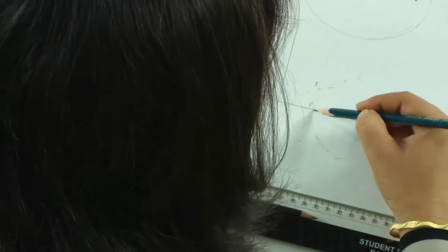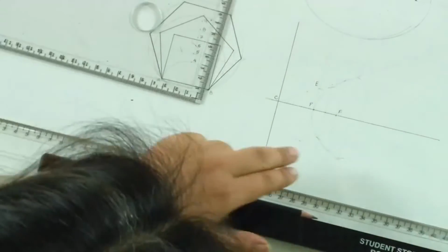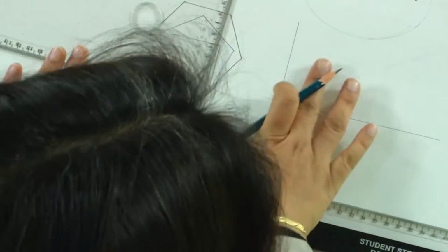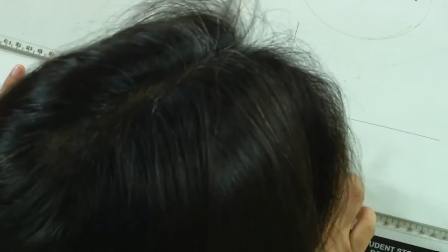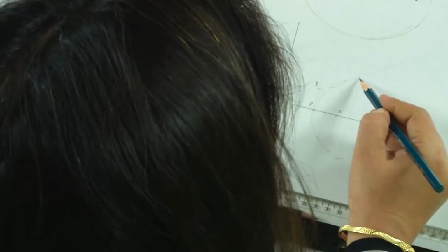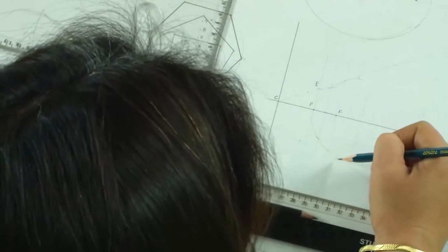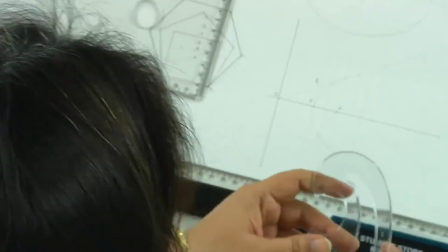This is what I am getting. But how do I fix it? You can draw a complete ellipse using the same method. However, I am only showing you how do you fix the curves. For this, what we'll need here is a French curve. I'd already shown you the French curves. There are, if you notice keenly, there is a number written on each of these curves.